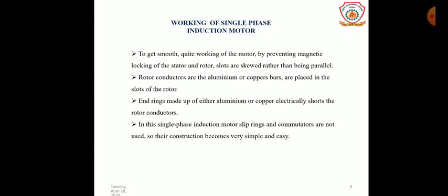In the single phase induction motor, a single phase AC supply is given to the stator winding. The stator winding carries an alternating current which produces a flux that is also alternating in nature. This flux is called the main flux. This flux links with the rotor conductors, and due to transformer action, EMF gets induced in the rotor.